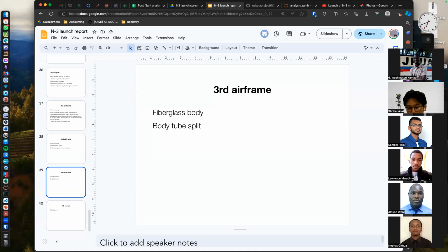However, now you are putting a surface close to the nozzle, so with the higher pressure inside, instead of diffusing, it creates an external pocket of higher pressure due to the compressibility effect of the proximity of that deflection plate to the nozzle. So the whole thing amplifies and affects the normal flow from the rocket.